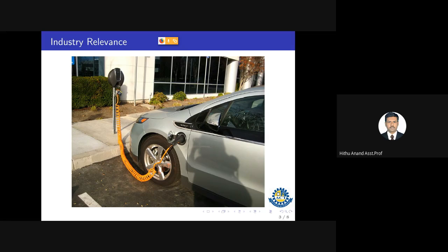You have to find the load profile of the industry and do the calculation, and you will get a value in horsepower. Your motor capacity is always measured in horsepower. So 1 horsepower is equal to 746 watts.